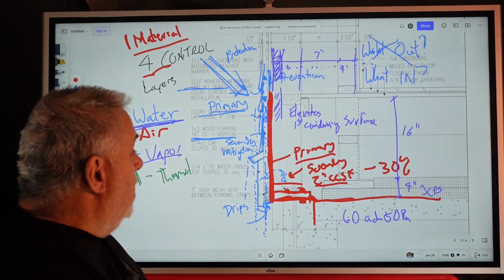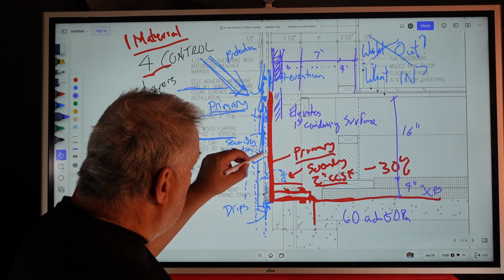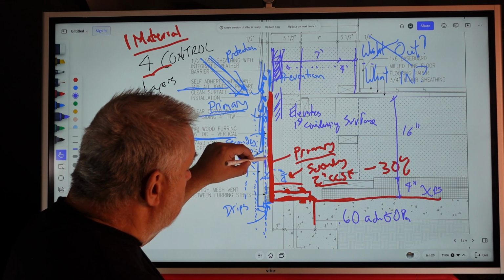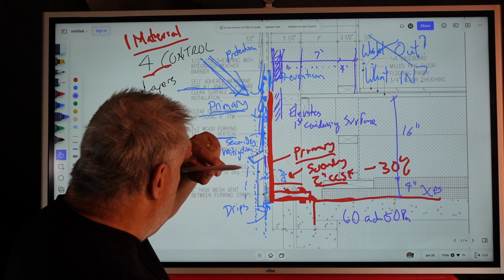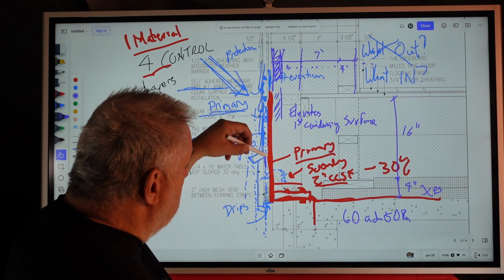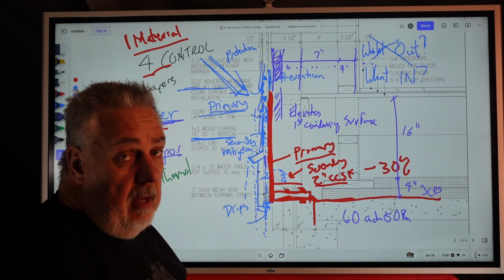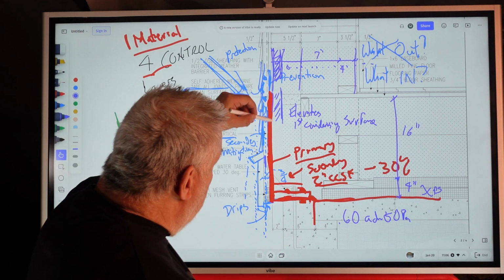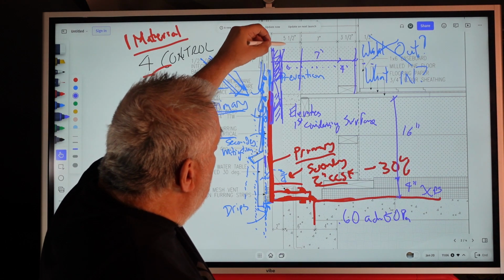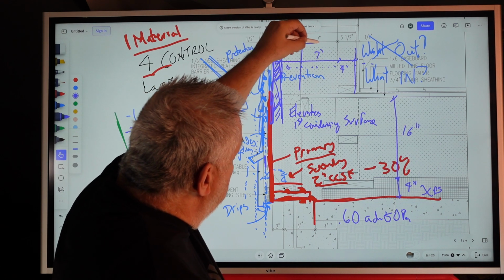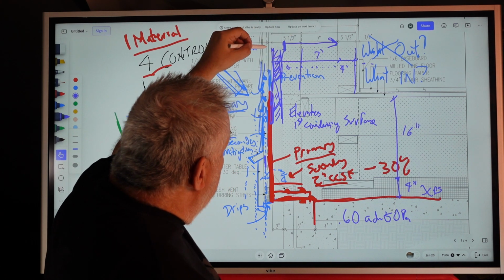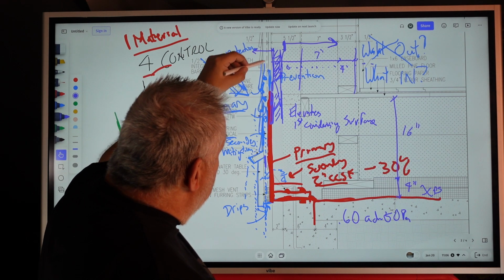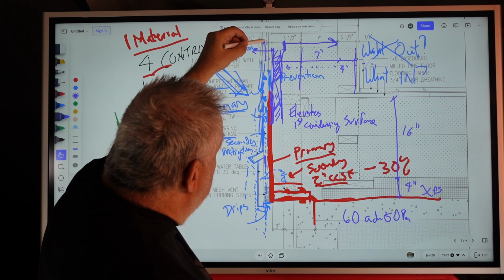Now, one of the other nice things about having the 3/4 inch airspace here is, the minute we put that closed cell in there, people are going to say, well, you restrict the drying in the wall system, right? Well, we do. We restrict it at this point here. But now our wall has the ability to dry from here to the inside. And on the other side, it can dry to the outside as well as that 3/4 inch airspace.